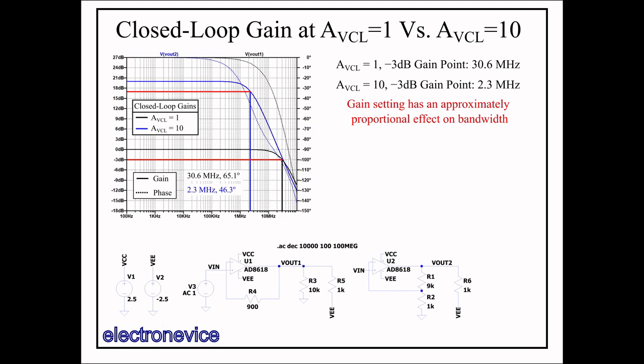The deviation from the ideal gain that occurs at high frequency is, as we might expect, due to the loop gain getting too small to enforce the ideal gain in the same way we saw in the previous video with the finite gain infinite frequency approximation, which is why the negative 3 dB bandwidths for these two configurations are fairly close to the unity gain bandwidths of their respective loop gain transfer functions.